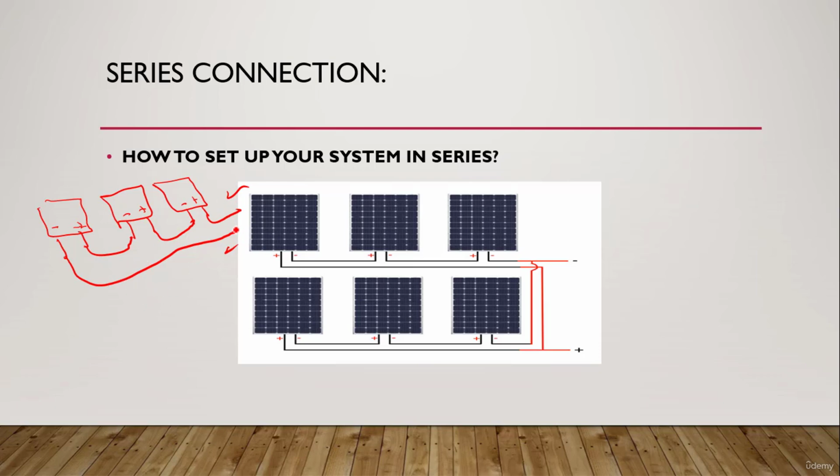In this case, the current in the entire 3 PV modules is going to stay constant. On the other hand, the voltage across the output is going to be the summation of these voltages, according to Kirchhoff voltage law.